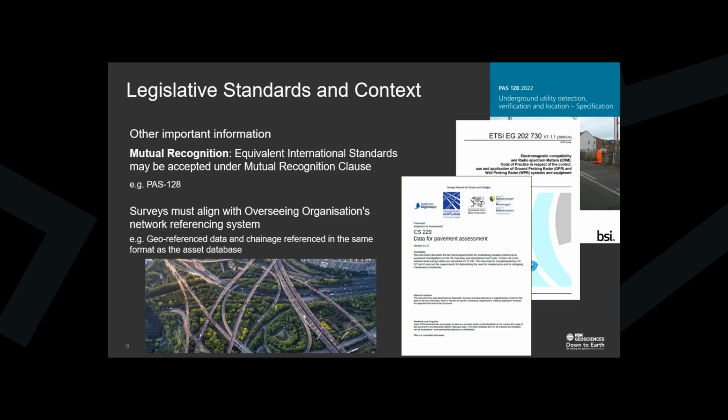So looking at the relevant standards and legislative restrictions, there are several that cover the use of GPR. GPR surveys on public roads in the UK must operate within specific legal and technical frameworks. So we've got the radio licensing. Although we try to always direct the radio energy into the ground, and the transmit power is very low, probably a fraction of a mobile phone transmit power, the GPR system is technically broadcasting radio waves.